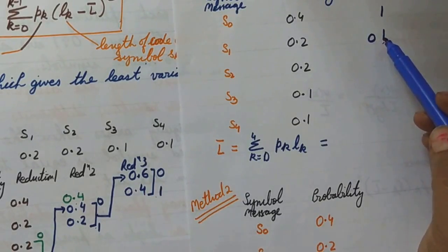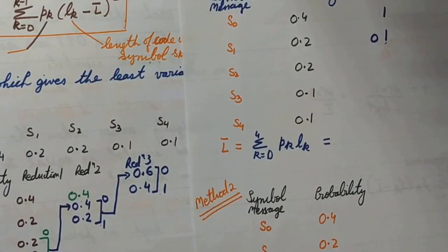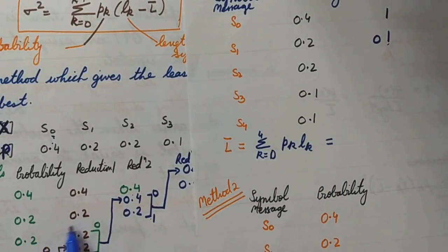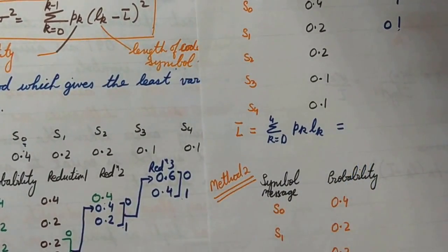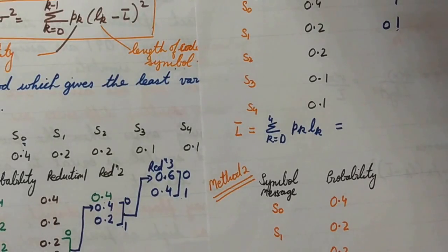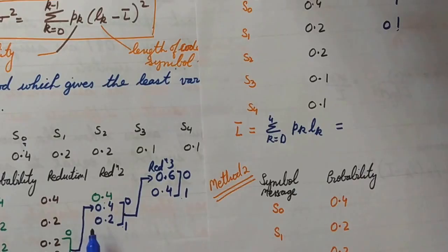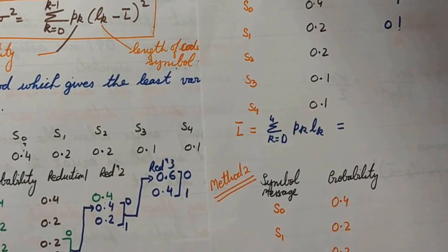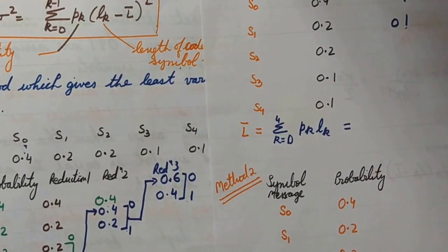So it means that in the order in which you are moving from left to right, whatever bit you are getting, you write in the opposite order. Means the first bit which you get from left to right, you make it the last bit, the LSB. And as you keep on moving, the last bit which you obtain from left to right becomes the MSB.